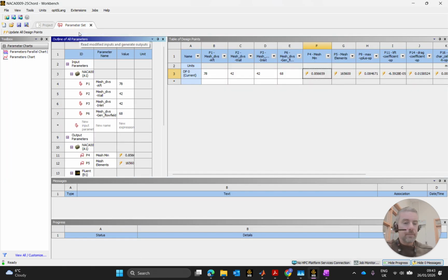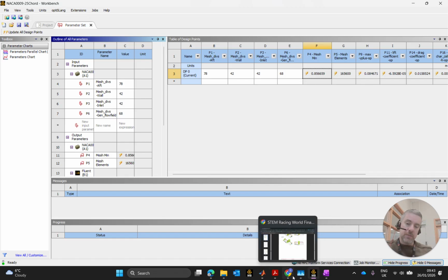Okay. So I've coarsened my mesh extremely here as well. I've reduced the number of divisions, so instead of having an awful lot of wee divisions, I now have fewer divisions, which has given me bigger chunks, bigger cell sizes. I'm going to make this here my coarse mesh. So what I want to do now is create a medium mesh, which is going to be one refinement order greater than the coarse mesh.